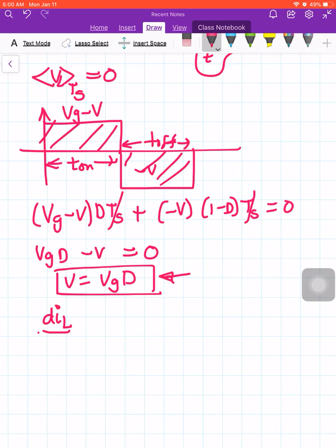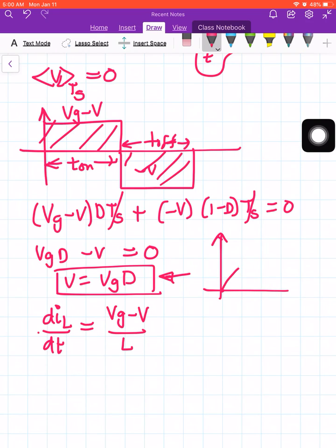So the beauty here is, as we said, when you are under the time scale of a switching time period, the inductor current is just a linear slope that we have seen. Actually, the slope should be following an exponential curve.